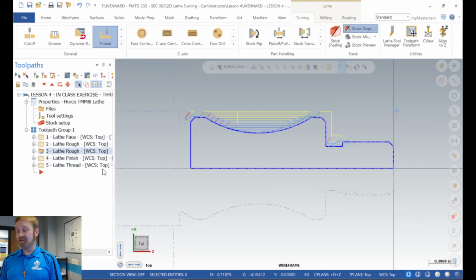If I would see that red on my verify screen, I'm doing it. Now, I'm not going to lie to you. I can't tell you how many times I've been at the machine and had to hit the button, and then I go look at Mastercam like I'm an idiot. Why didn't I run this through verify? I'll see where there was a retract move that didn't go up high enough, and it runs an end mill across the top of my part. I've done it enough times to know better, and to know that this doesn't take very long to do, but I just get in a hurry and don't run it through.